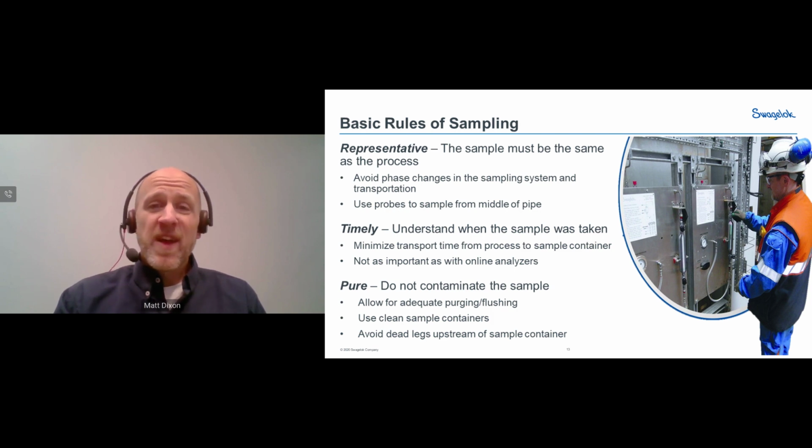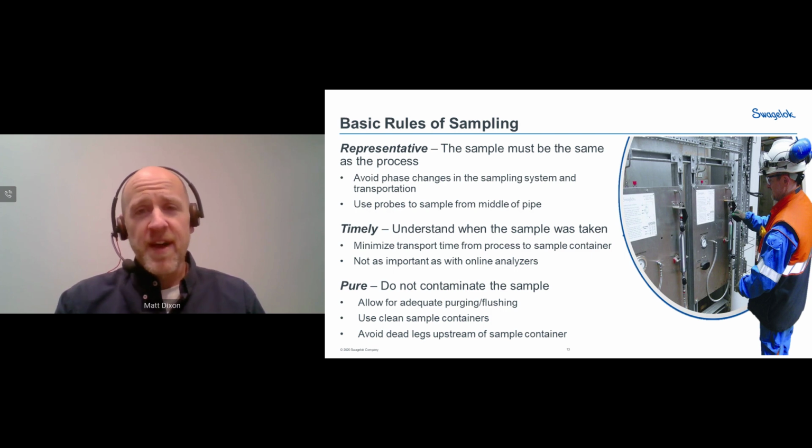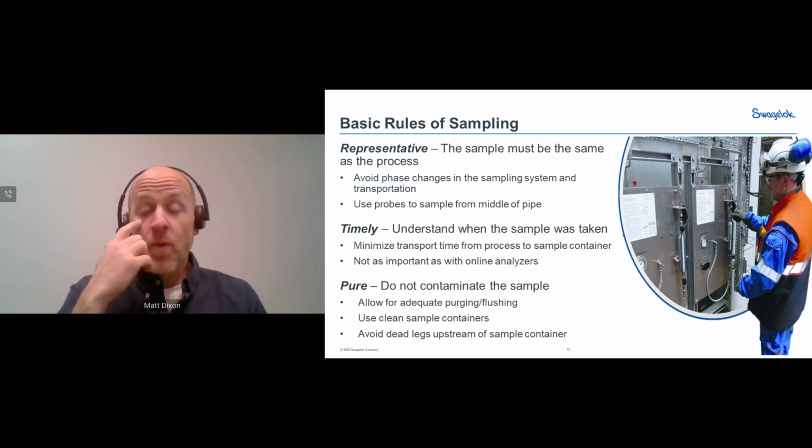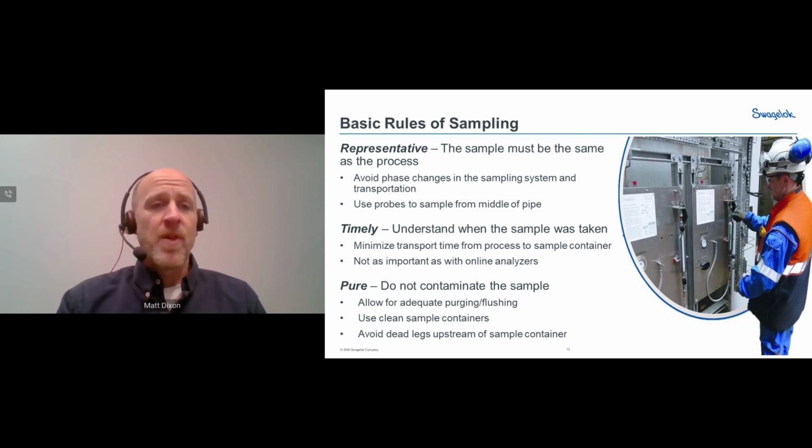We want to avoid phase changes. Generally not a problem with viscous liquids. We generally don't have to worry too much about changes in phase, well, with the exception of solidifying. Normally, when we're talking about changing phases, we're worried about changing from a gas to a liquid or vice versa. We don't have to worry about that, of course, but we do potentially have to worry about solids and plugging.